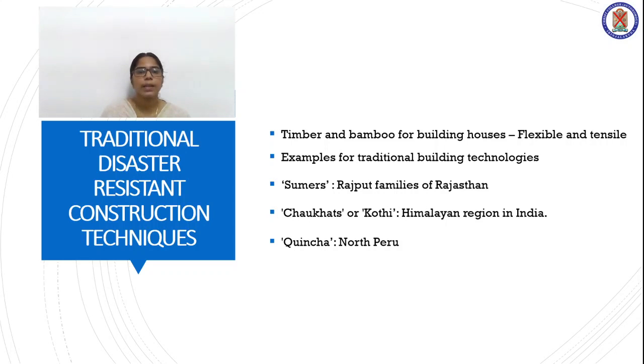Avoiding compression structures like domes and arches is another option. The structural system needs to be tensile and the material should be flexible, as is the case with timber, steel and bamboo. It also helps if the structure is constructed in a way that it vibrates as one unit and sways together during an earthquake. Most new constructions with heavy roofs of slate, tiles or RCC supported by weak walls have proven to have a deadly effect in earthquakes.